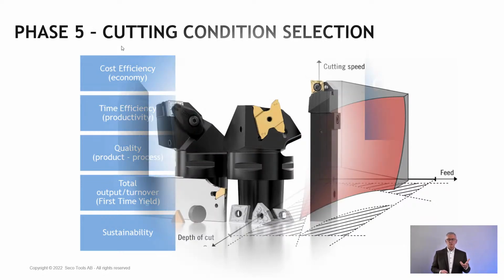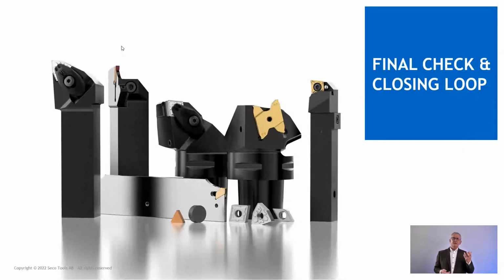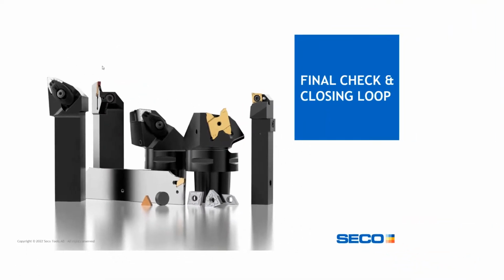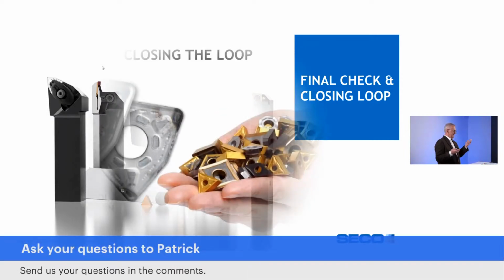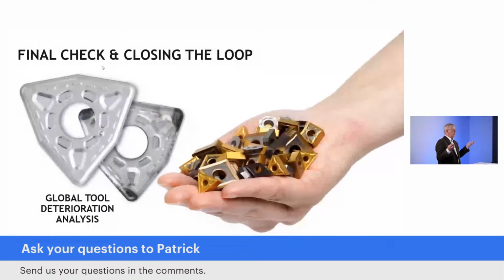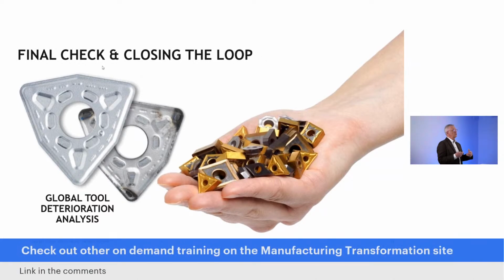With the 5th step comes the final check, kind of closing the loop. And I already said, in machining, I consider it from a pragmatic perspective. How do you know you did a good job? How do you know that every step led to the wanted result? Watch the tools. Watch the tools after they did the job.